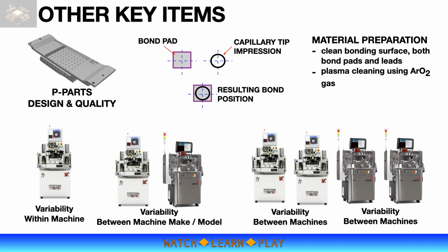Preparation of devices for bonding is important. As we say, garbage in, garbage out. The devices have gone through many process steps. Bond pads and leads may have been contaminated along the way, either from handling, exposure to environment, and epoxy outgassing from curing die-attach epoxy.